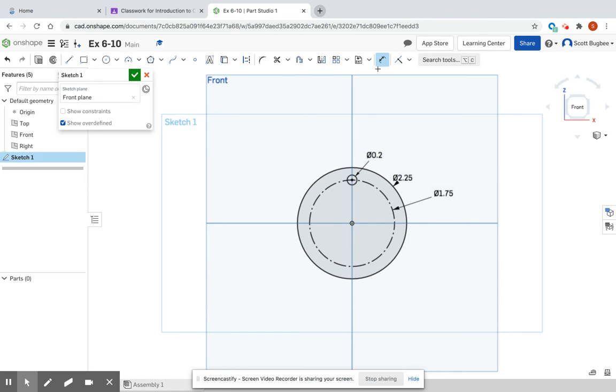From here, I can use the circular pattern tool. It is listed here with the linear pattern tool. So I will select circular. I will select my feature by left-clicking that I want to pattern. And by default, it automatically picked up my axis, my revolve axis, and it automatically puts in 3, which I could change if I needed more than that. But I don't need to change that. I like what I see. I left-click again, and it creates those circles for me.